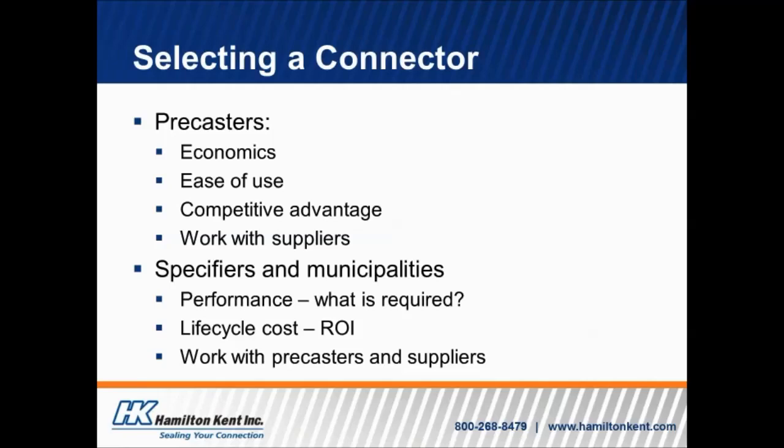Then from the specifiers and municipality side, really I think the most critical things are going to be performance, obviously. What's going to perform well in the field, what's going to give them long-term strength and durability, and what kind of requirement do you want to have? Do you want to have a 13 PSI type requirement or a 6 PSI okay? Life cycle cost: what's going to be the return on investment for requiring that precasters start supplying a watertight connection for stormwater, and there is going to be some type of requirement there.